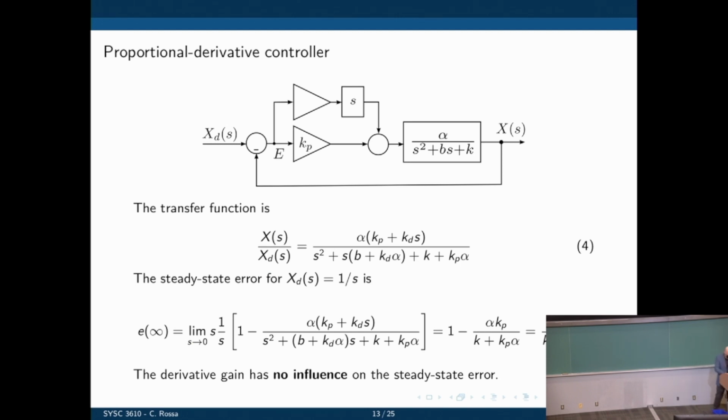And that's precisely what we see in the equations. This is KD. That's the transfer function between the input and output. Same equation we used here to calculate the error for a step input, limit of s of the desired input minus the transfer function times the desired input. That is the 1/s factored out there. We have the result in the calculation, and if we simplify this, I will just rewrite here for those that are at home, since my image is overlapping. There, that's the result.